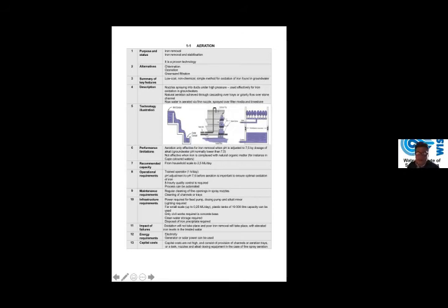So you need to increase your pH as well. Otherwise, often the pH of this water coming out of the boreholes could be 5 or 6. And at that pH, you're not going to achieve much when you use aeration as your oxidation option. A recommended capacity up to 2.5 megaliters per day, so more on the small treatment plants.